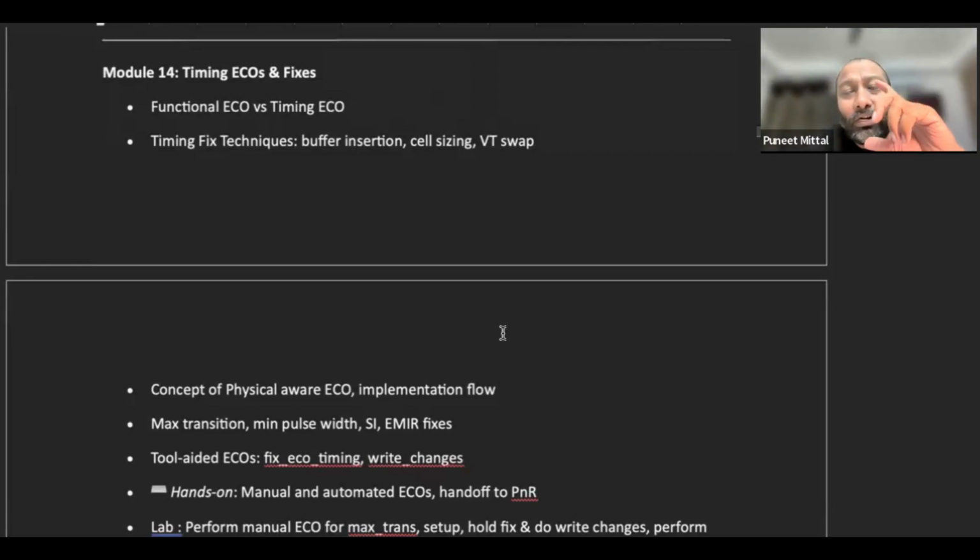It is going to do the analysis, not change anything in the design. But if you come across a cell giving you more delay and you want to change the cell to reduce the delay, virtually maybe you can do it in the analysis tool, but you have to make the changes in the design. For that, you have to go back into the design and do it.